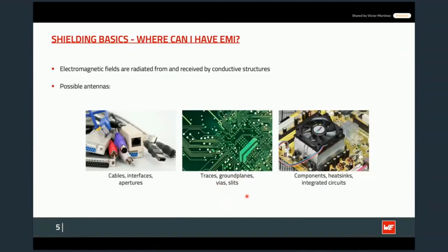And also it is not only something really physical or something that you create on your PCB. Also, we can find that some basic components can provoke an antenna, like in this case a heatsink, which at the end is something that is only there to dissipate heat.